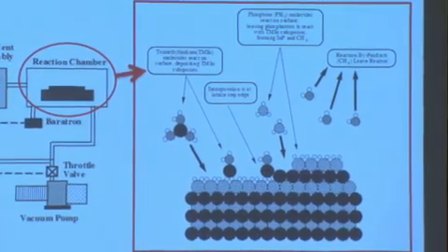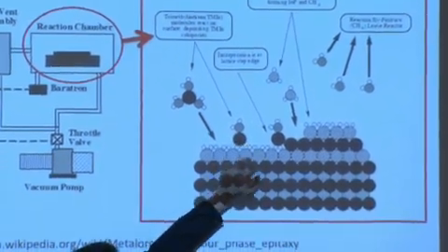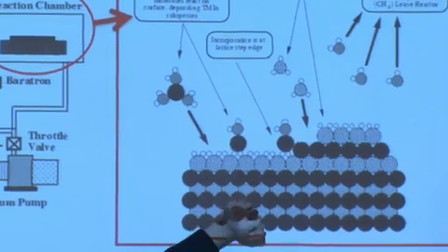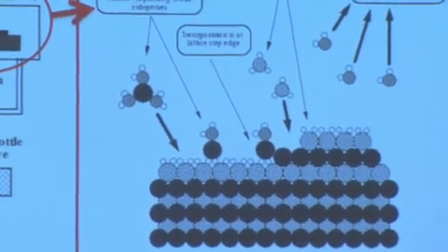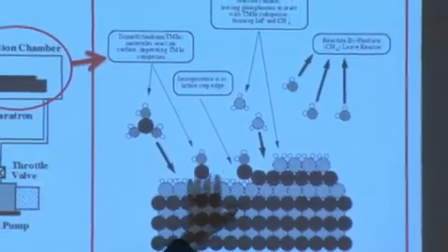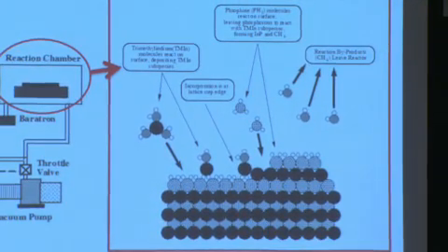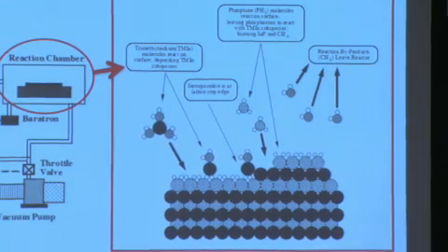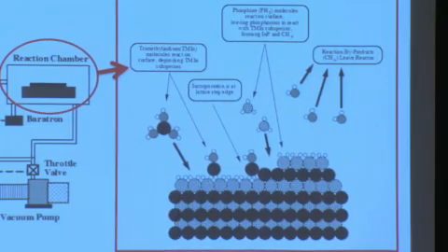This represents right here the separation, where we have the indium atom shown in black right here. And then the methyl groups are moving off, and essentially those will be sucked out of the chamber, leaving behind, in this particular case, a layer of indium, forming probably another layer of material underneath. Say, for example, your other species comprising the thin film may be phosphorus, so it would be indium phosphide growth.